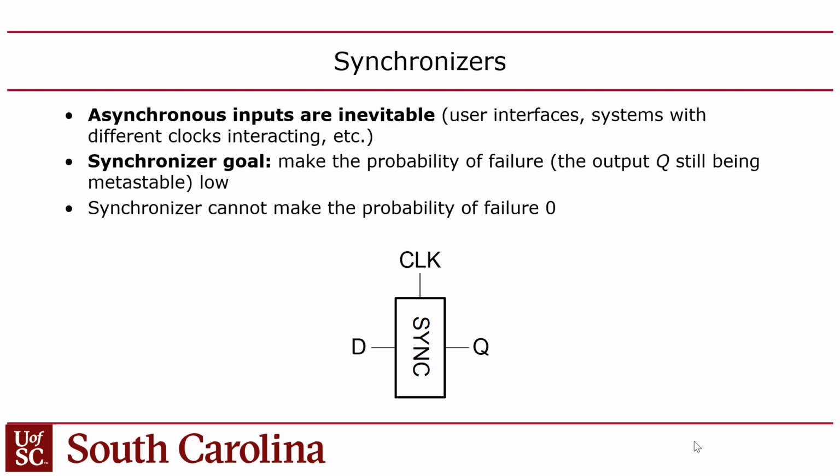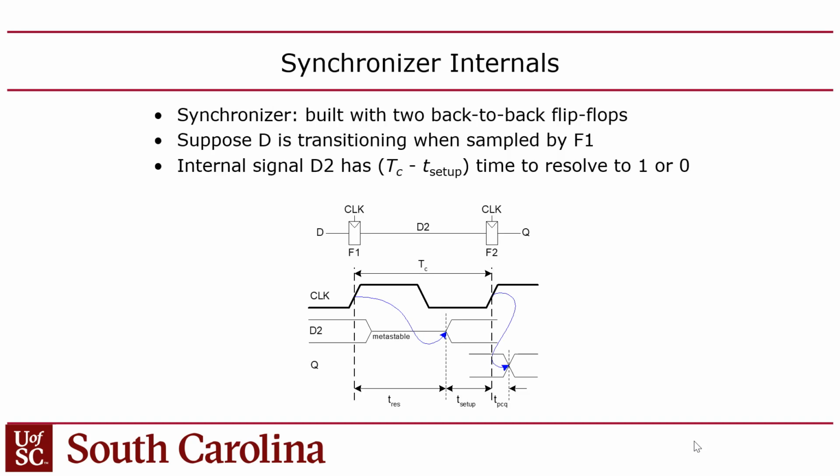Okay, so there's this idea of a synchronizer. A synchronizer is where if you have an I/O pin, and by the way, there's no other choice, if you have an I/O signal, you have to put it into a flip-flop, right? But in order to reduce the chance that you'll have a bad input value, you can put another flip-flop in series. When you do this, it's called a synchronizer.